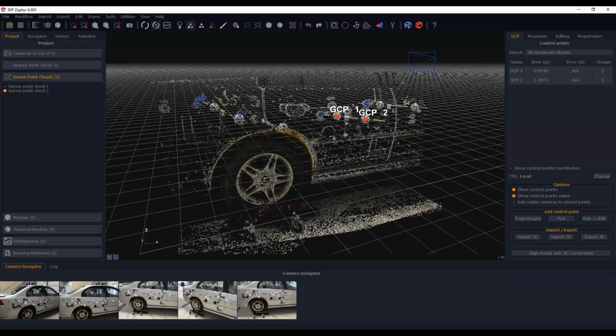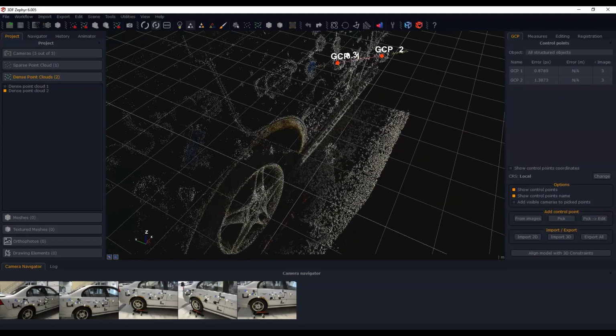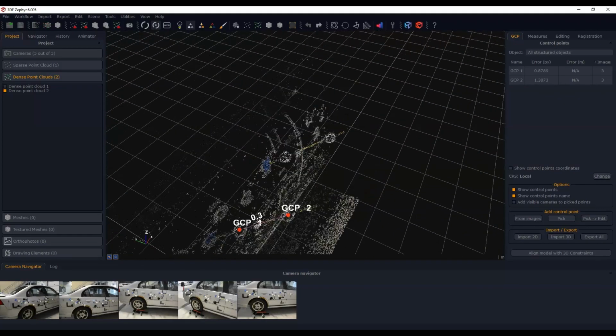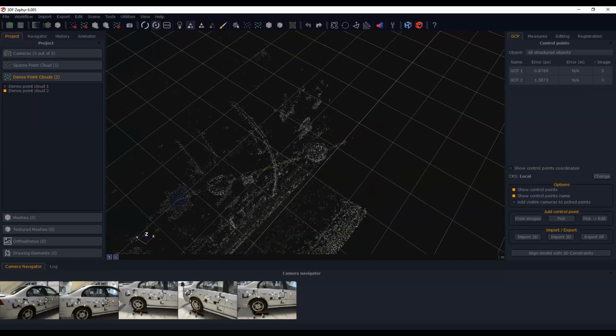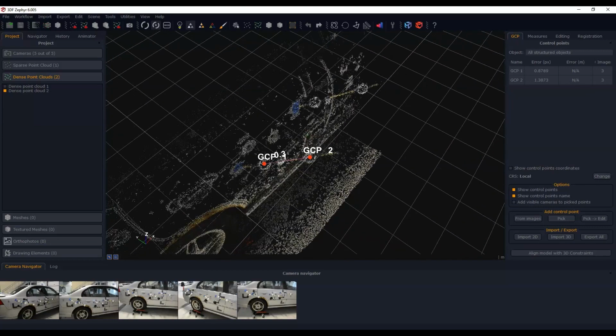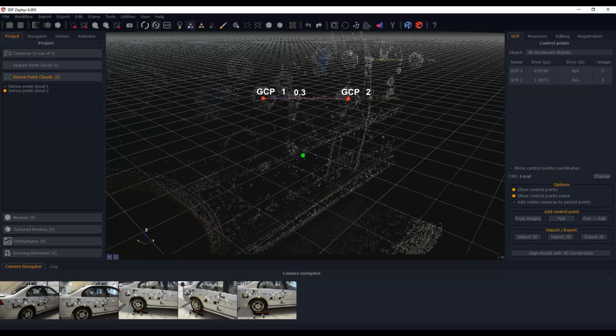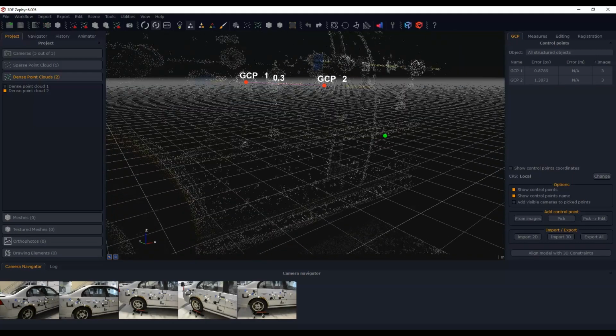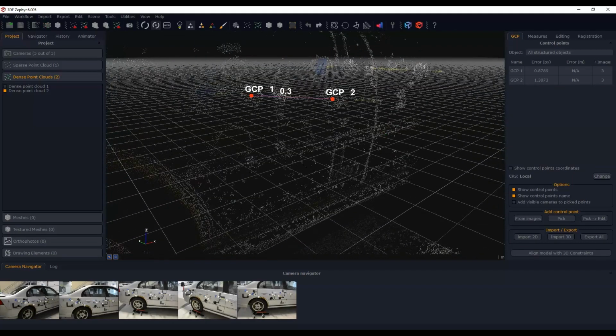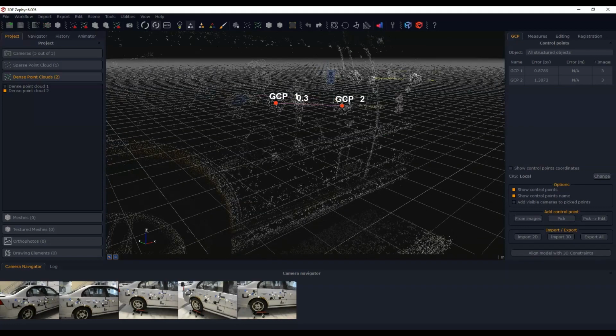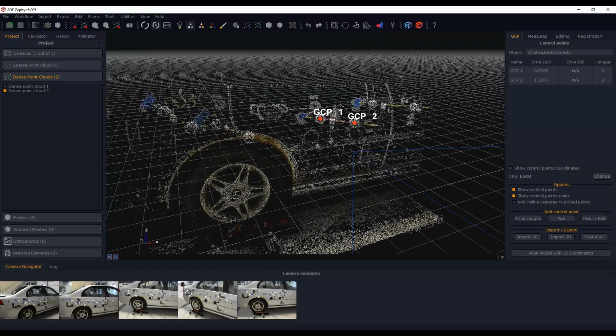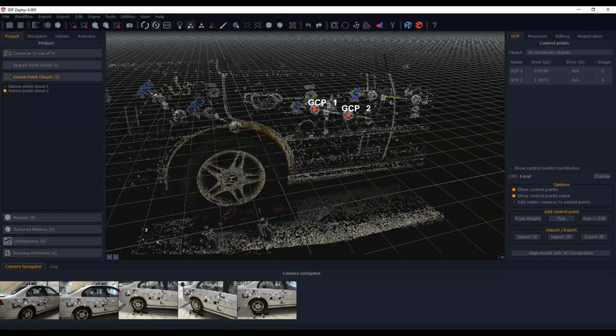If you look back here, you'll see that in some cases the rod is kind of noisy. And even over here, okay, this one's not too bad. I did okay there. But you'll see here you're missing parts of the rod, and it just becomes a little bit more subjective when you're trying to pick these trajectories. So that's how you would do it with photogrammetry. Now let's start the data processing of the laser scanner, and I want to show you exactly what happens to those rods with the scanner.